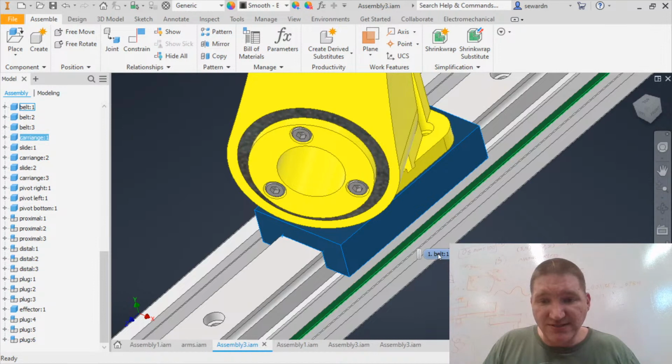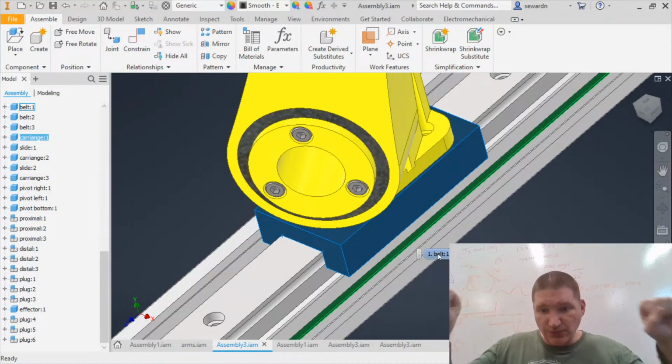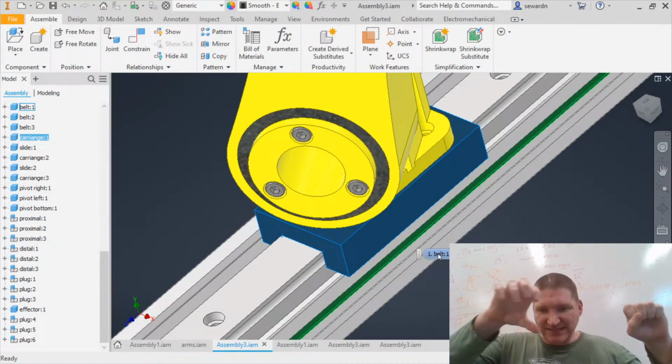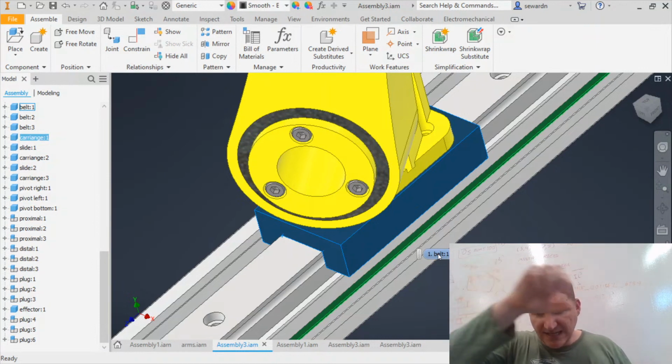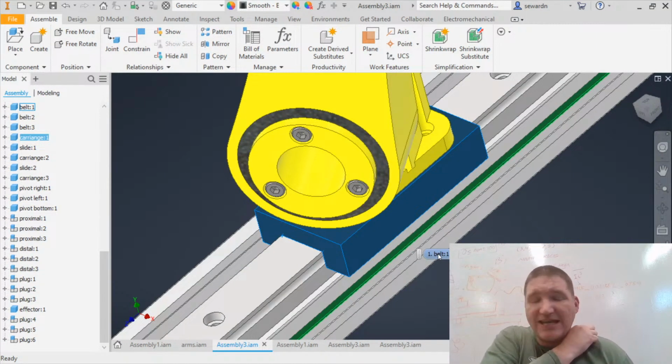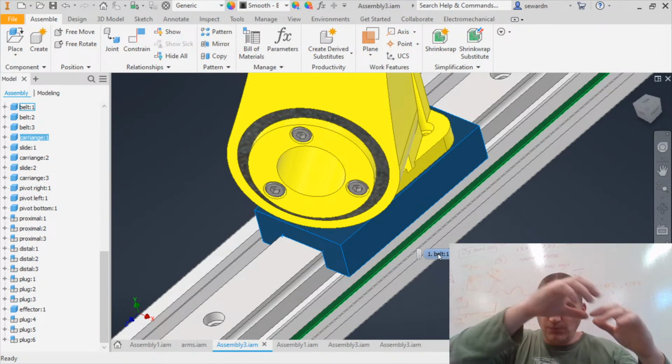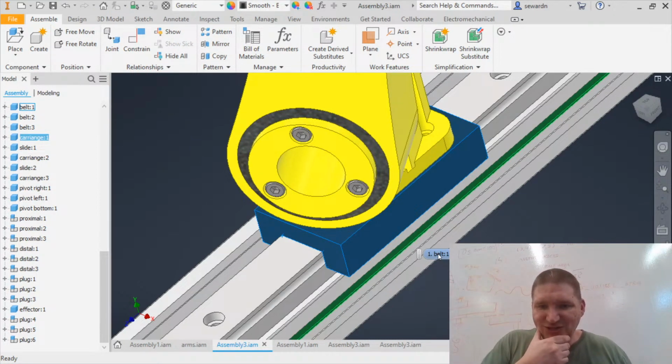What are some other options though? You can do a rack and pinion, of course. One of my favorite ones is you can have a static screw, and then you could have the stepper with the nut on the inside of the stepper, and it could turn and move along the static screw. That way you can actually have one screw and multiple steppers along that, so you can have a shared axis. That's really cool.